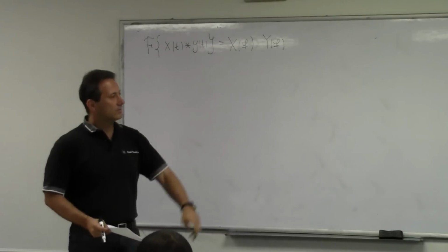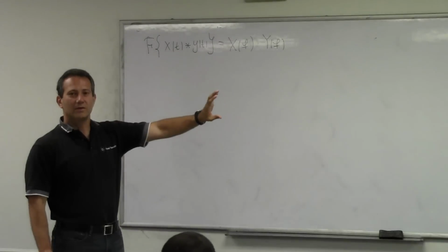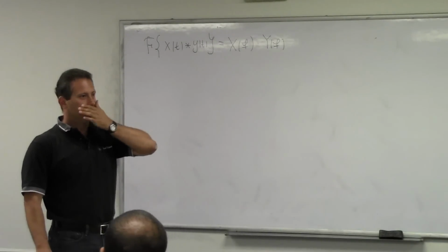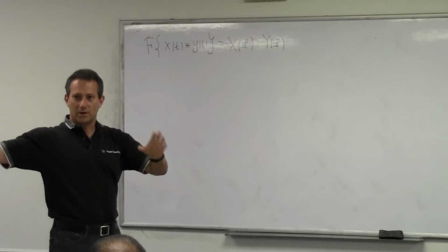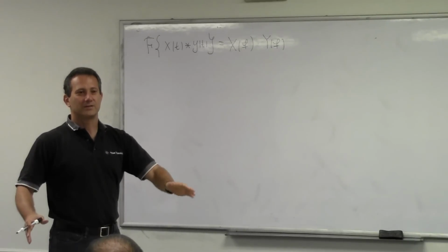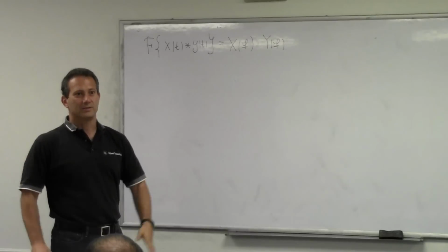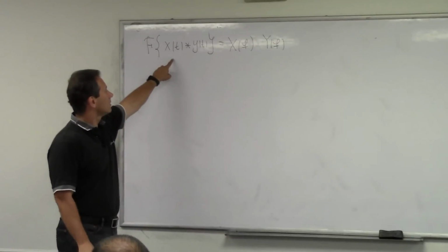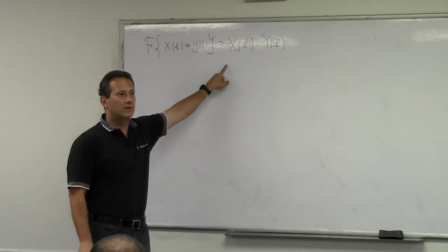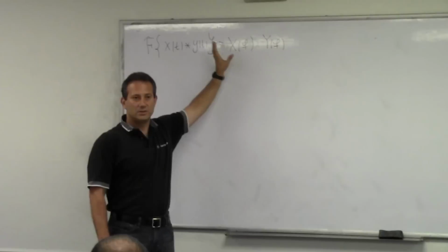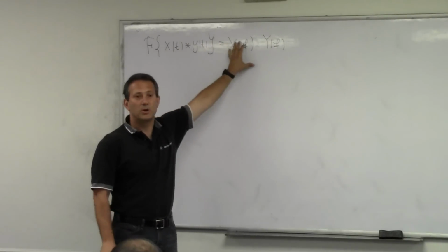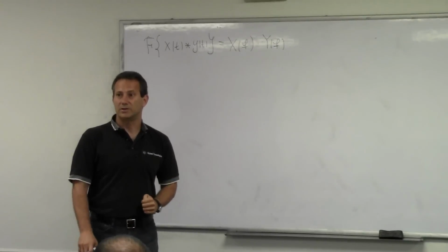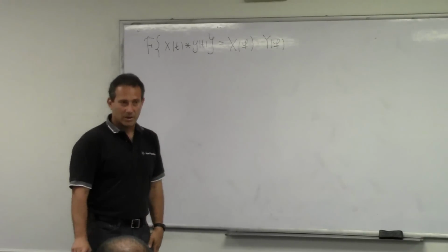It takes something that we tried so many times and never learned to love, and that's the convolution itself. Whenever you need to do convolution, you sit, you go get a coffee, and you know that you're going to spend the next 15 to 20 minutes trying to crank this integral, right? Well, what this tells us is if you have the Fourier transforms of individual functions, the Fourier transform of the convolution is just the product of the Fourier transforms. Product is a point-by-point operation. You can actually do it much easier.